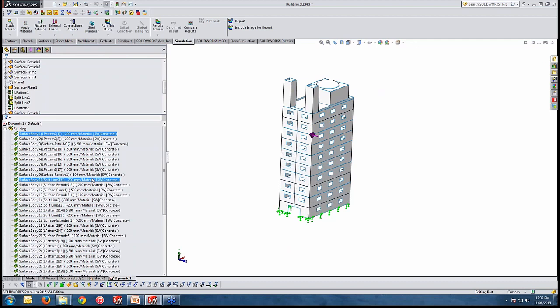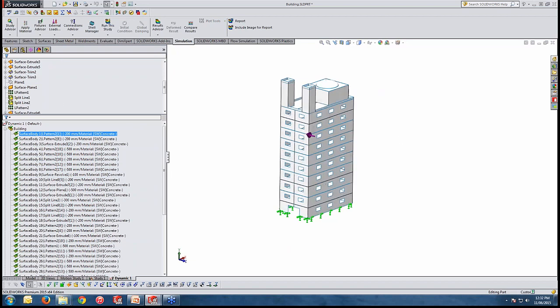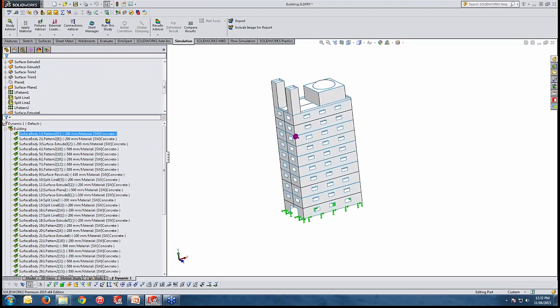That is all defined, but again, if you are taking a surface CAD geometry and it's going to be converted automatically, it is more than important when you're doing such a thing to make some simplification to the model and make it meaningful to your FEA study, rather than having a very detailed representation and spending a lot of time on unnecessary calculations.